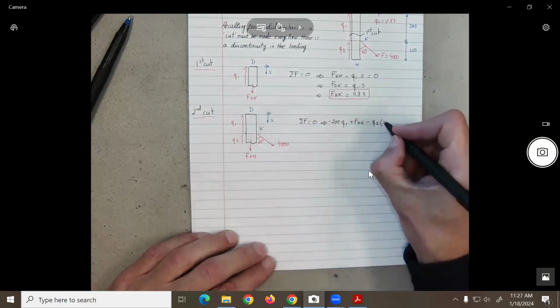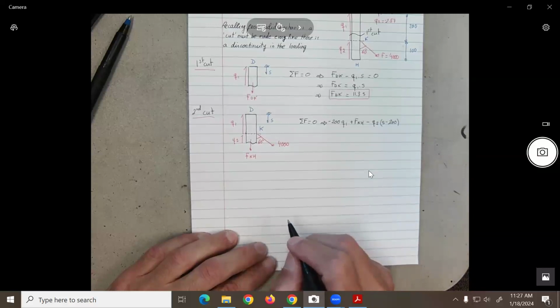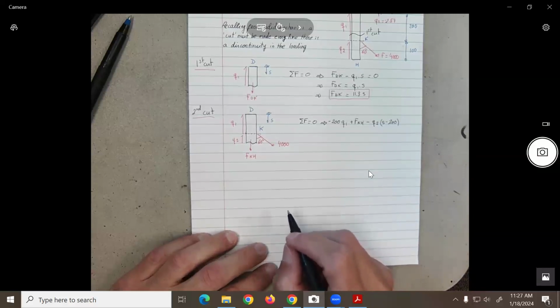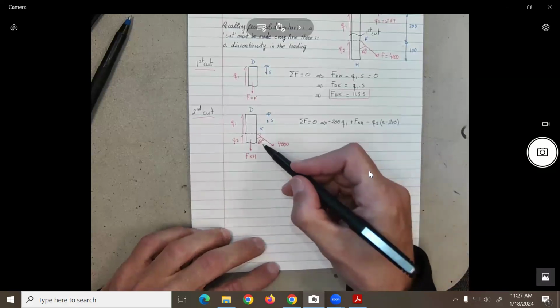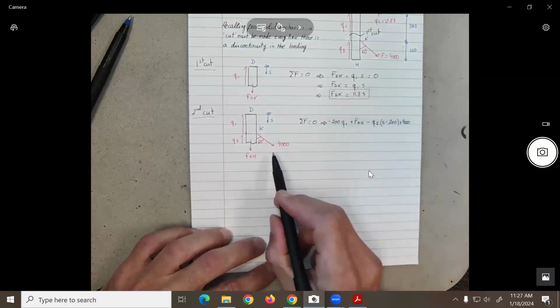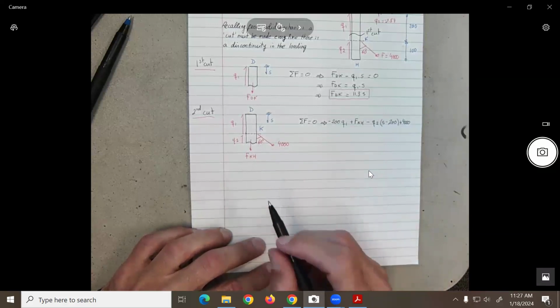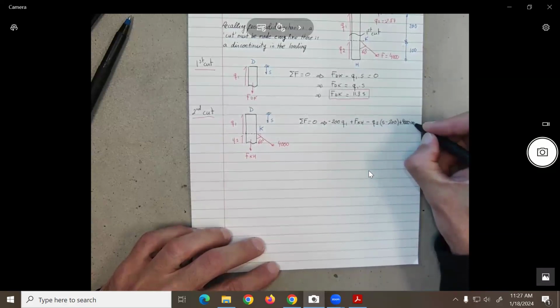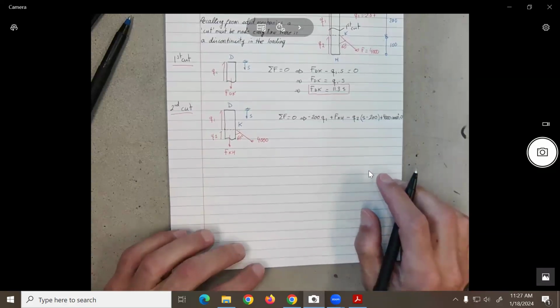So what is that? S minus 200, no? Okay? And now we don't have to forget this one. Plus the 4,000, we need to take the component of the 4,000 in the vertical direction. So it will be cos 60, and all this stuff should be equal to 0. Sorry to make it that small, but I was running out of space.